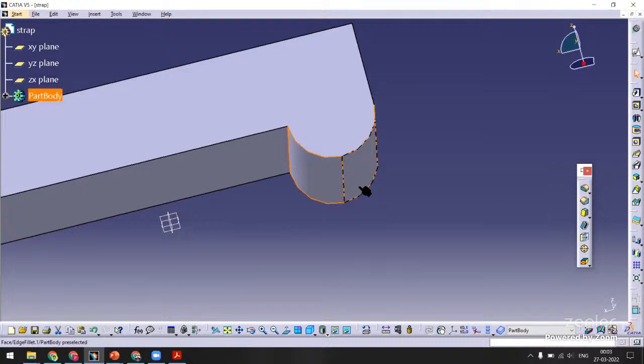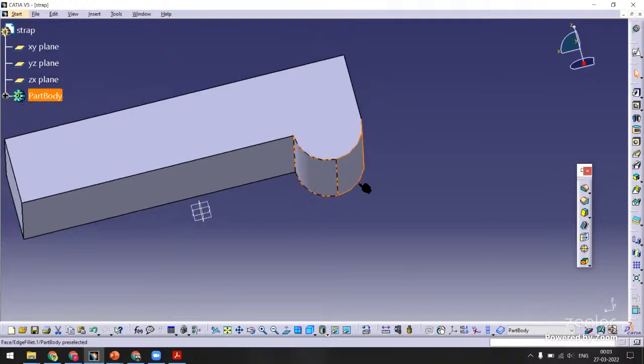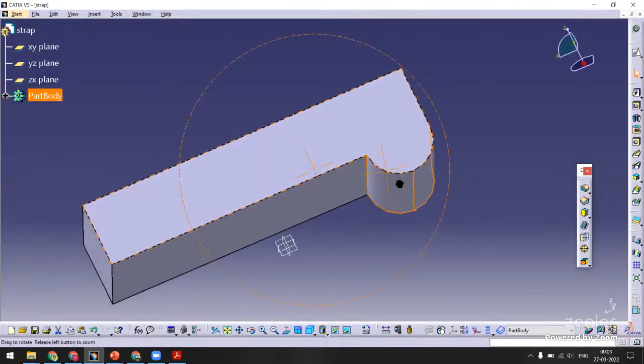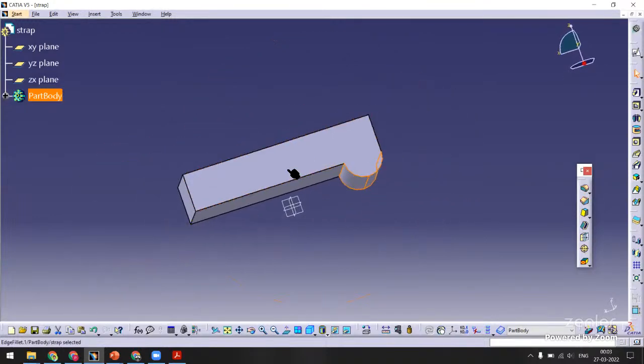However, both of them are material removal processes. They are going to take time. But making a curved shape would take more time than making a straight face. So chamfer from the manufacturing point of view, radius from the functional point of view. So you can go with either the chamfer or the radius.